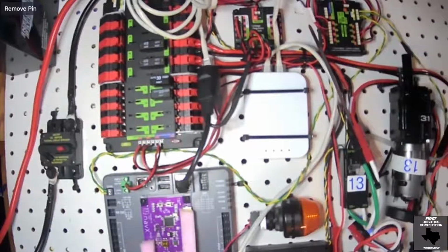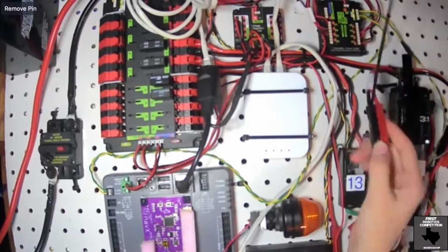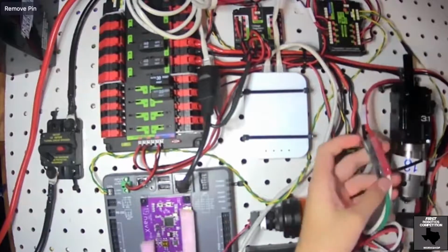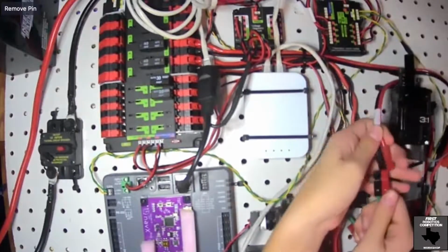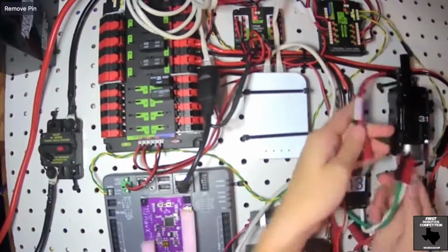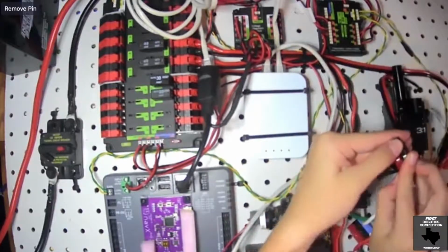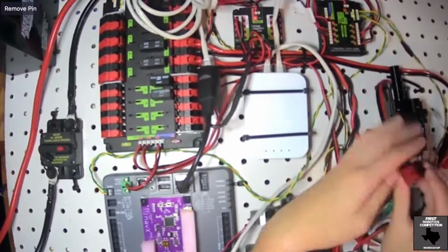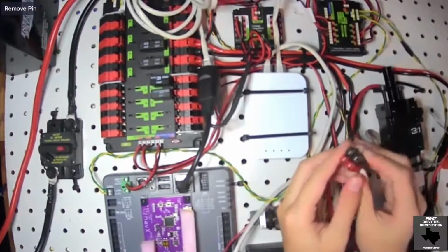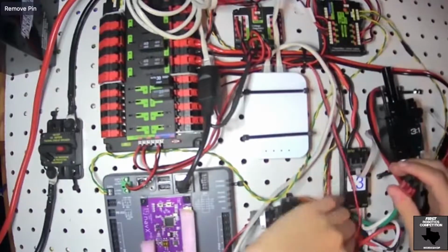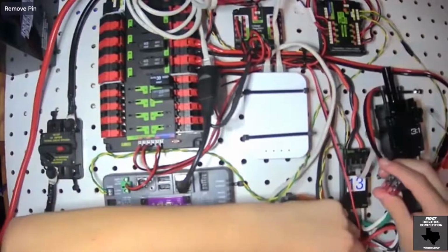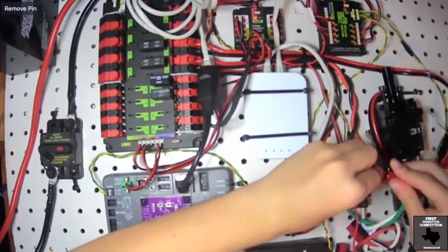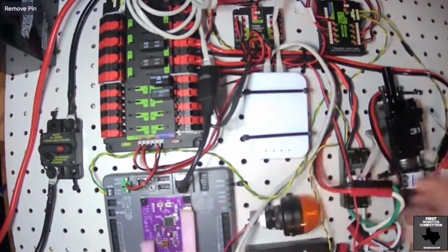So the only other thing I'm going to talk about is Andersons. If you haven't heard of Andersons, please do research on them. They are the universal wire connector. They come apart, they plug back in together. The cool thing about them is that you can take bunches and you can stack them. So we used to have huge bundles of Andersons on our robots. And even when it's like this, you can still plug in another Anderson to them. So Andersons are really awesome. They can get a little pricey, but they're 100% worth the purchase.